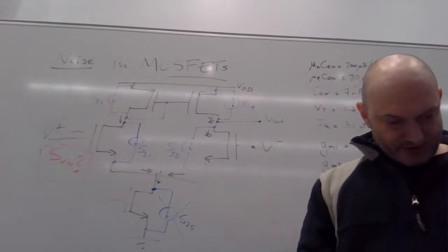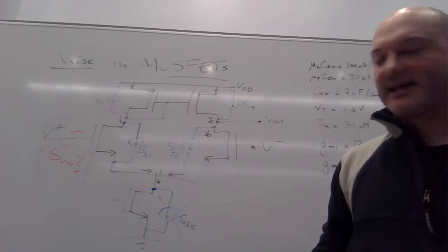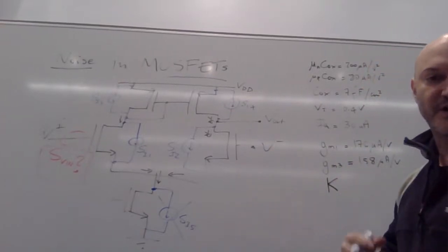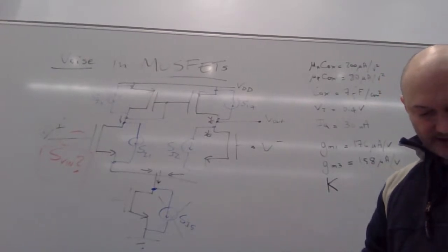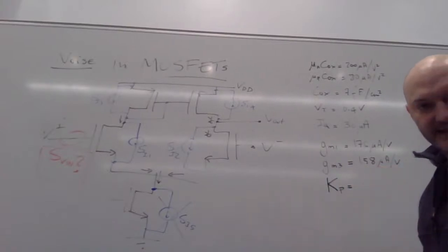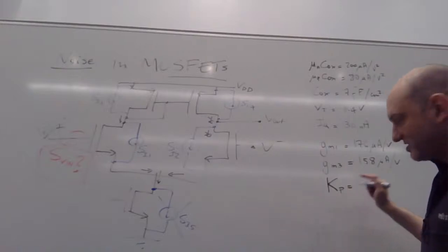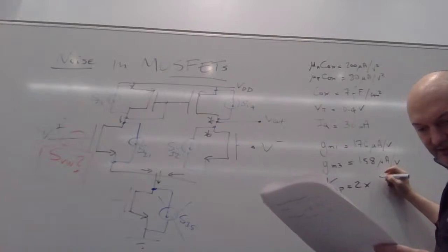Right, so if we put some numbers in, now we need to have the constant K. And the constant K depends on the type of MOSFET, whether it is p-type or n-type, and normally in silicon MOSFETs, the constant for the p-type MOSFET is considerably lower than the one for the n-type MOSFET.